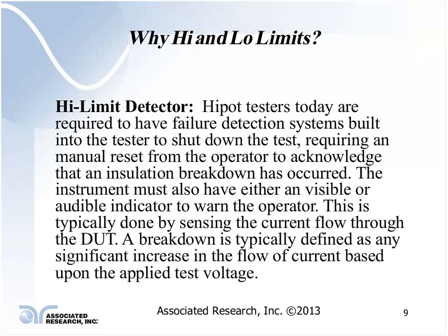It was being done by another operator who happened to be standing on the opposite side of the line, who let out a scream when the Hipot test was conducted on the product. It turned out she was performing a continuity test between two panels on the product at the same time that the Hipot test was going on. Both operators could not see each other because of the size of the product. It was setting on the line and it blocked vision from one side to the other.